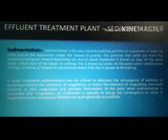So next topic, sedimentation in the effluent treatment plant. Sedimentation is the process of allowing particles in suspension in water to settle out of suspension under the influence of gravity. The particles that settle out from the suspension become silt, and in water treatment this is known as sludge. When a thick layer of silt continues to settle, this is known as consolidation. When consolidation of sediment or sludge is helped by mechanical means, this is known as thickening.